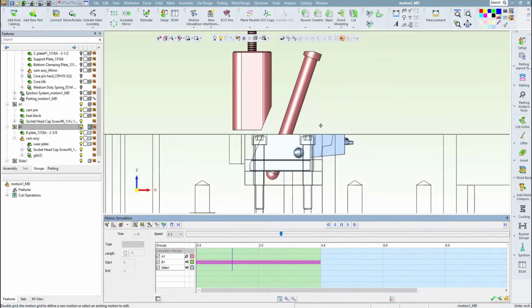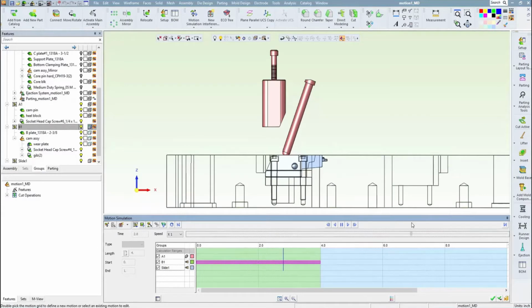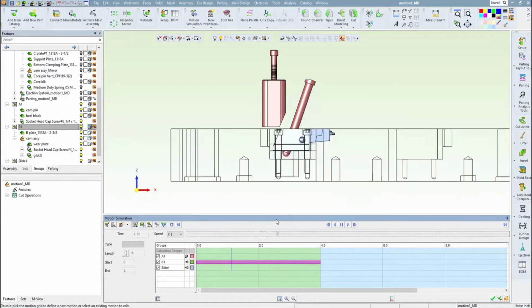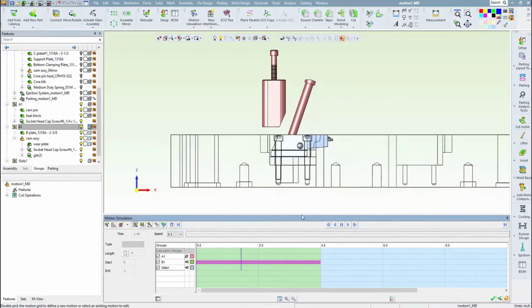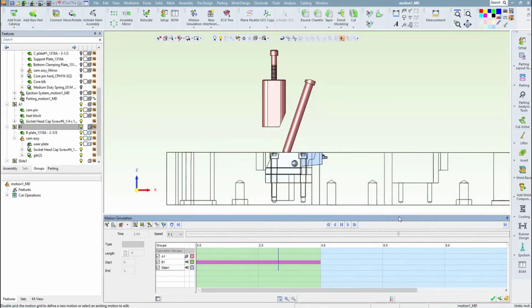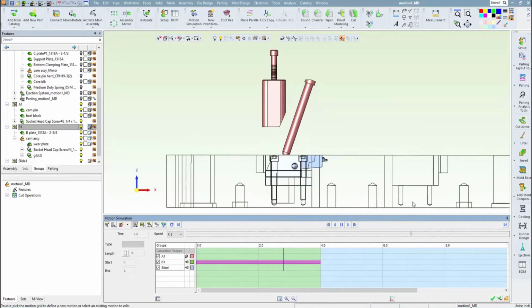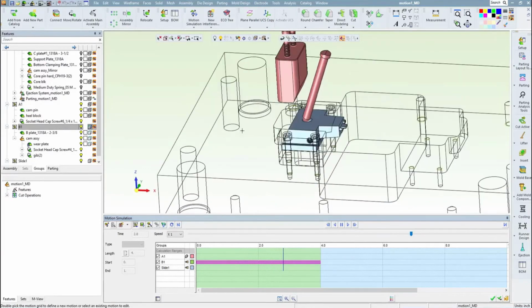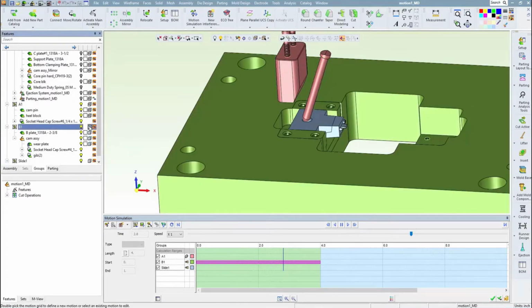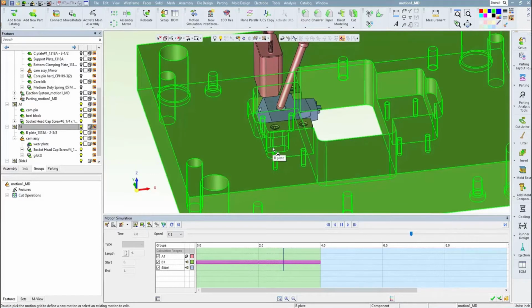Here, as the mold continues to open, the slide actually keeps moving to the left, and it drags the plate and the entire B-side group over with it. So despite the vector on the B-side group telling it to move downward, the forces of the objects interacting can still cause motion in a different direction. This is kinematics at work and is what the system will always strive to do. Move the parts in such a way so that the motion can finish.